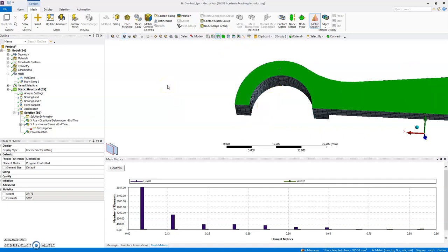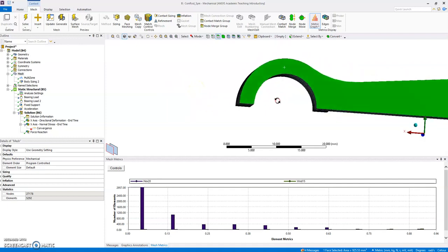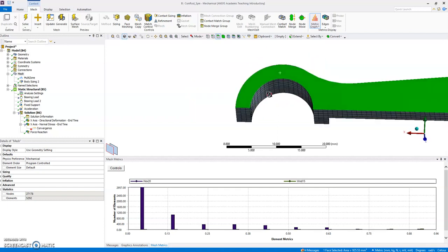It tells me that I need to go back to my CAD package, in that instance Design Modeler, and apply some face or add some bits of geometry, very likely some vertices here, so that I can then, once I'm back into Mechanical, select them to add my sizings or my refinements.